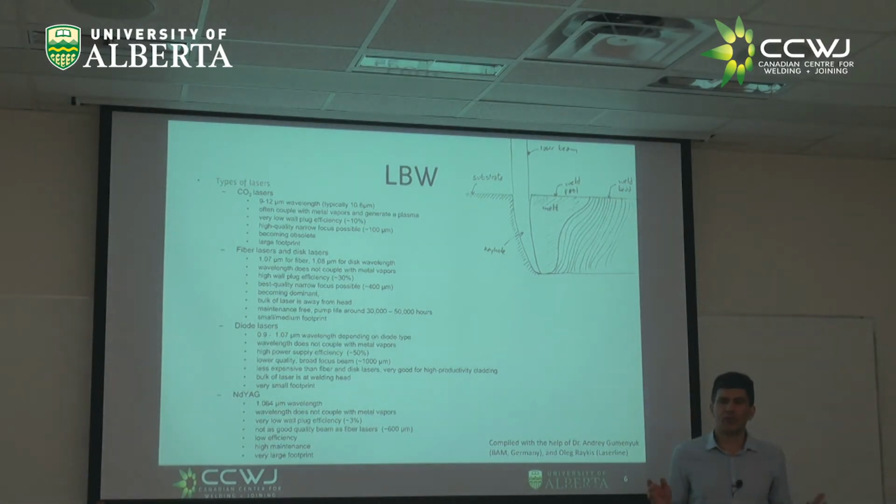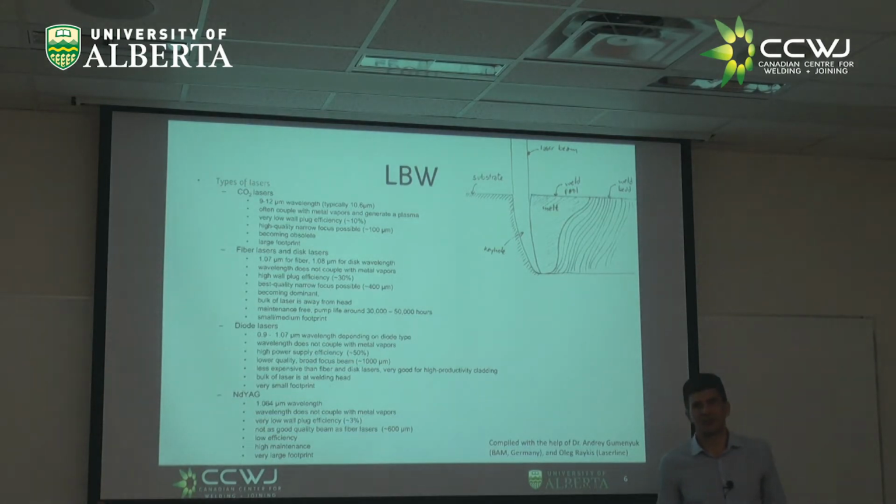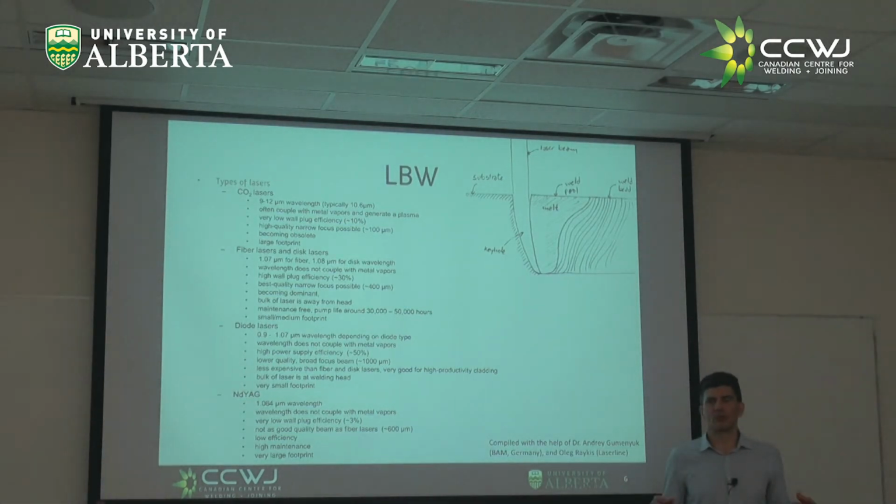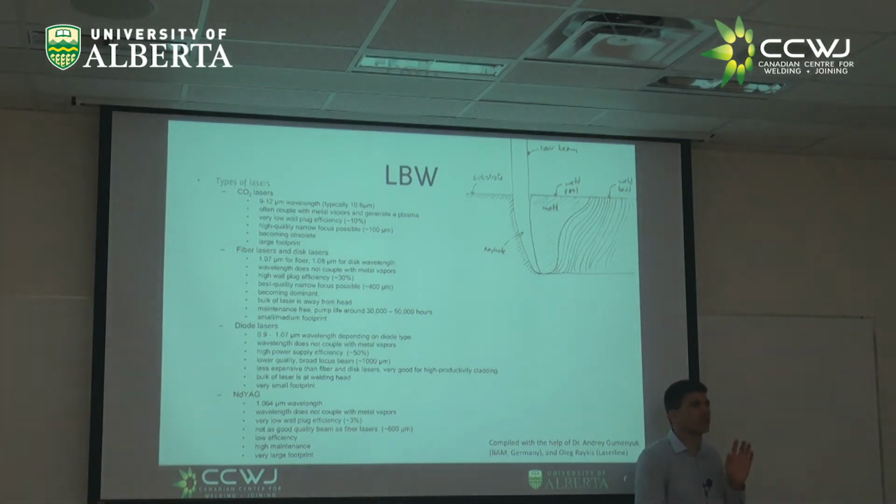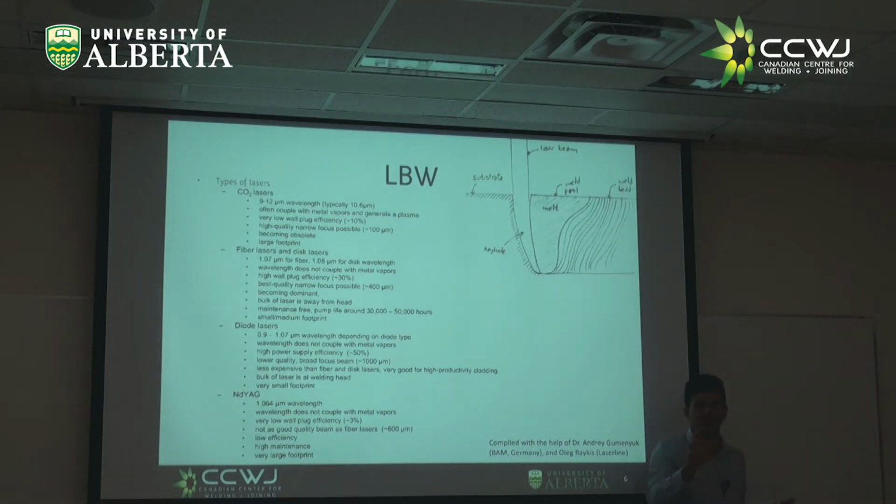Most things are not transparent to infrared. For example, I don't know if you know, those who took the heat transfer class with me, glass is not transparent to infrared. Water is not transparent to infrared, right? So you make your optic fiber. It has to be transparent to the infrared, right? And you can play tricks until it's transparent to the 1 micron. But transparent at the 10 micron, very, very, very difficult. So what they do in CO2 lasers, they use systems of mirrors that the laser shoots here and mechanically hits a mirror that hits another mirror that hits another mirror, right?